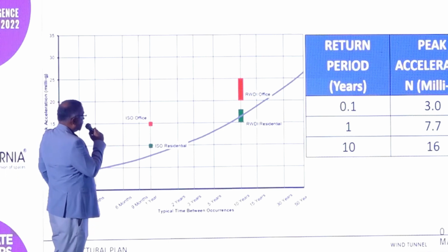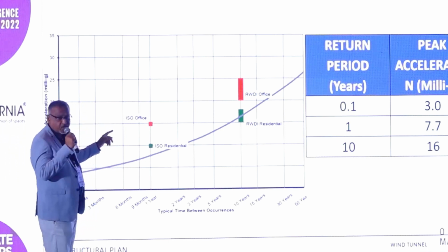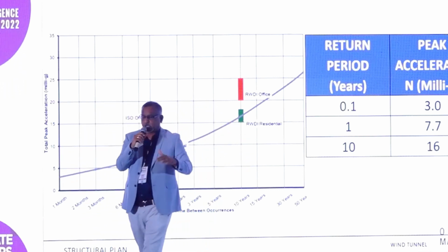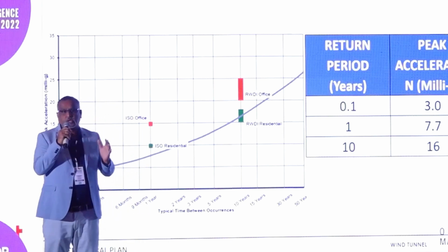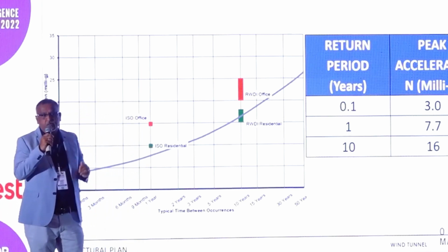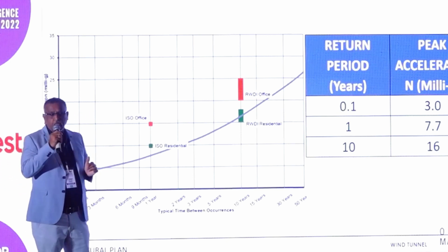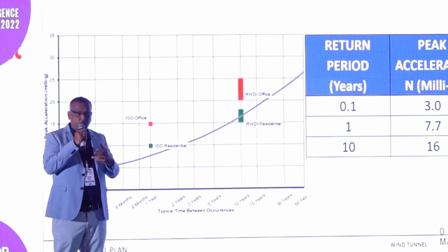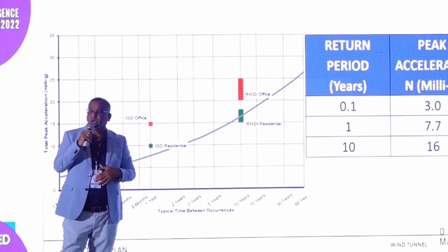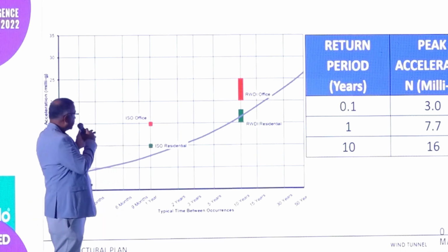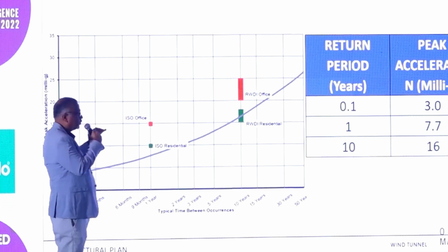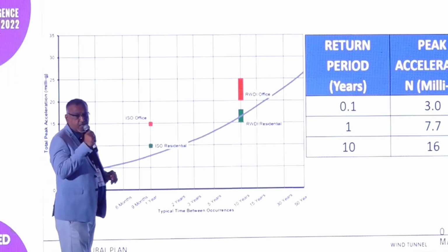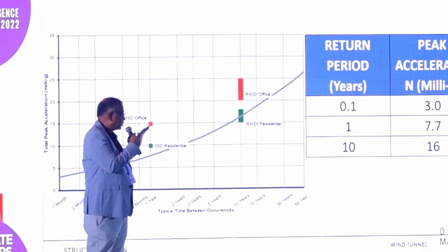This is about the wind-induced acceleration comfort criteria. So for this residential building also it is up to the mark, it is not exceeding the mark. Under extreme winds, the structure starts oscillating and accelerations are induced in the structure. From a safety point of view they are not critical, but from a comfort point of view they are critical. So different agencies, ISO, RWDI, give a particular value of the acceptable acceleration level. And then that acceleration level is achieved here.